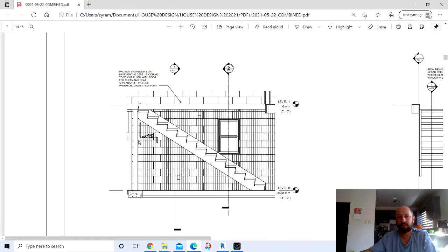And then this is the stairway. Here's your escape window and basement stairs. You need backflow preventers on yard hydrants. I went ahead with yard hydrants because I didn't want a pipe to penetrate those above ground walls for hose bibs on the wall, because the walls are thick, and then I just wanted to reduce the amount of penetrations above grade.